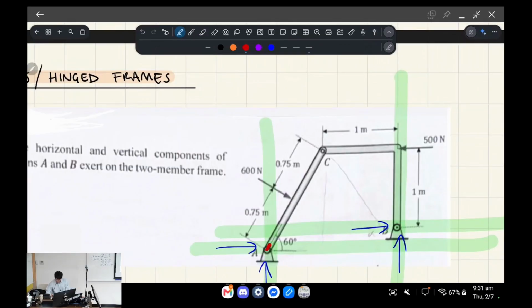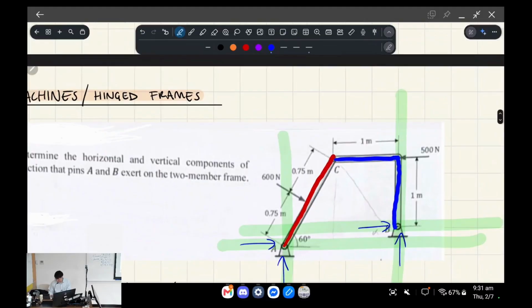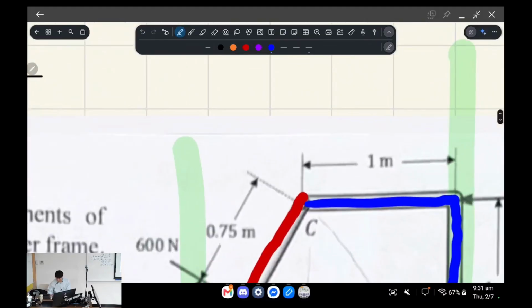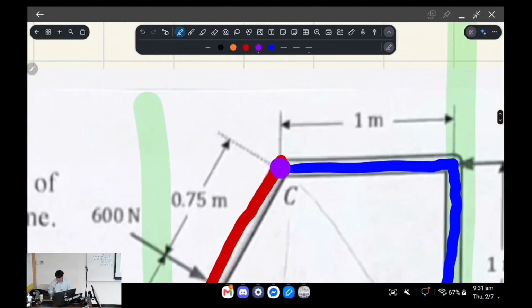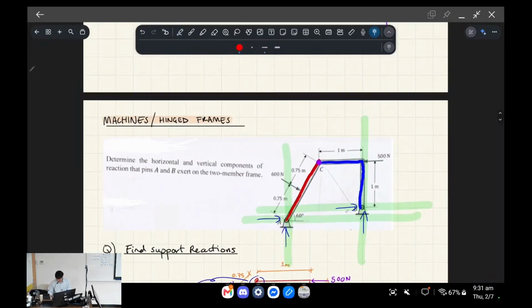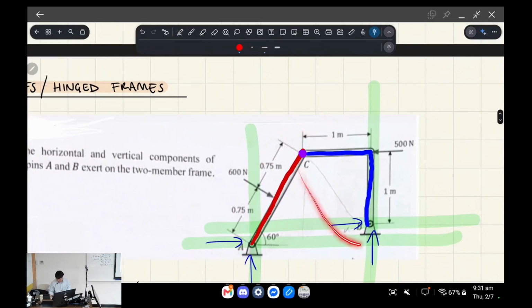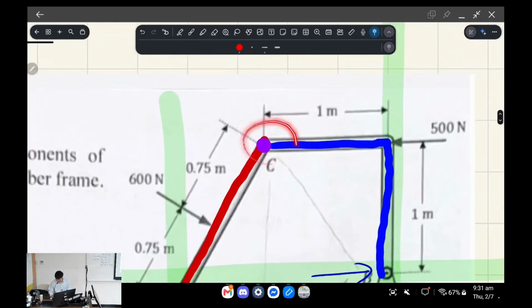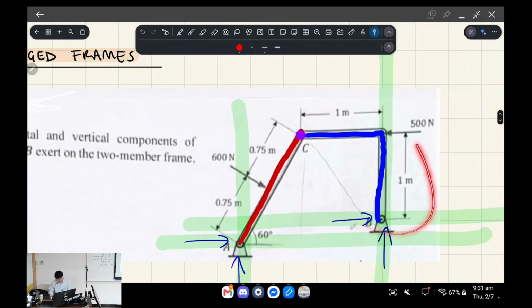The first one is this one-dimensional rigid body from A to C, and the other one is this 2-dimensional rigid body, which kind of bends like that. Okay, so from B to C. So these are connected by a pin or a hinge, okay? And what we essentially say is that we can split up the free body diagrams at this hinge connection and pretend that this hinge connection actually acts as a pin support, okay? For both the left and the right side, okay?